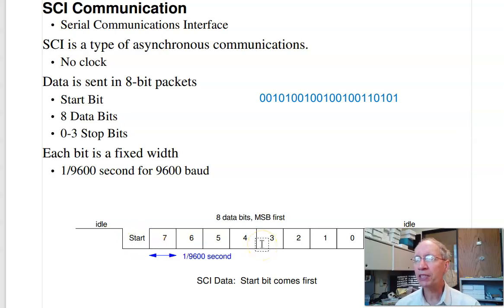Now transmitting and receiving are a little bit different. Transmitting is actually pretty easy. I just transmit whenever I want, but when I do that I have to pad the first bit with a 0 and end up the line being high when you're done.